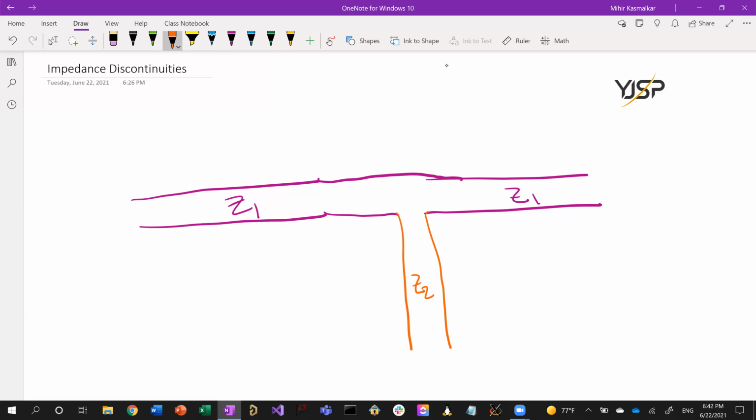This could happen if you have a multi-board stack, a bunch of stacked boards connected to some sort of stacking connector, but you don't connect one of the boards. You just leave it floating there. Then all the connections from the other boards going into that board will be a stub, for instance.